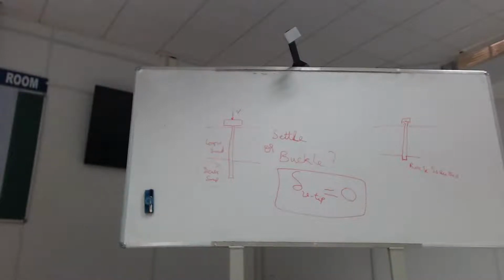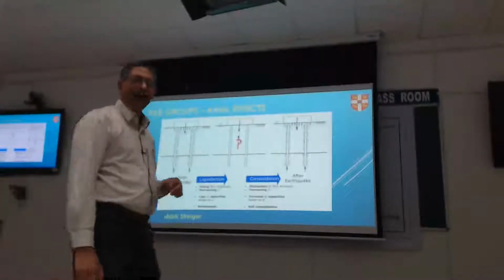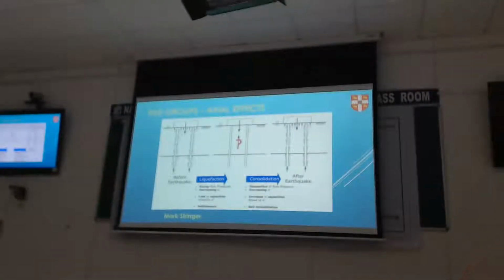Once we recognized this, we said, let's have a go at looking at vertically loaded piles in dense sand. Can we ever get them to buckle? And then we realized that actually we don't understand how the pile group and the pile cap share loads. So we know when we have driven the piles into the ground, made our pile cap and applied the load vertically, what happens? You've got a bit of base capacity, you've got shaft capacity, and you have some pile cap capacity. If I add all these three together, my vertical equilibrium equation says that should match the applied load, or should be more than the applied load to give me a factor of safety. That bit is dead clear.